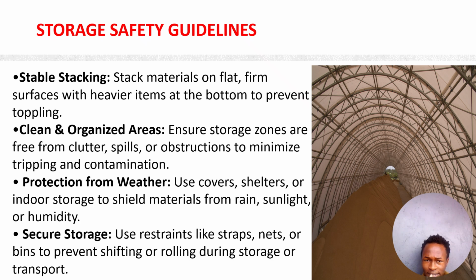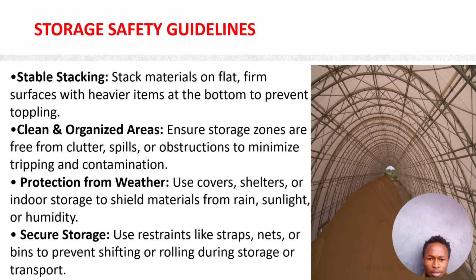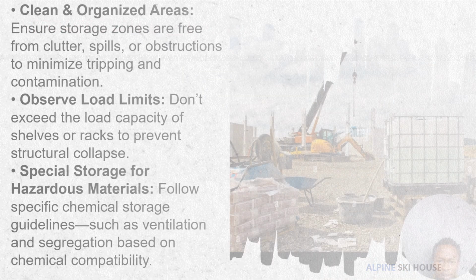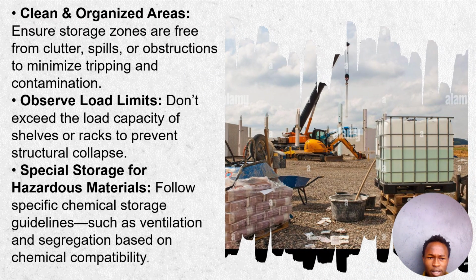Then lastly, I think our last subtopic of the day. You have other storage safety measures. You have clean, organized areas, ensuring storage zones are free from clutter, spills, or obstructions to minimize tripping and contamination. Then you have to observe load limits. Don't exceed the load capacity of shelves or racks to prevent structural collapse. And we have special storage for hazardous materials like cement and other adhesives that are used on site.